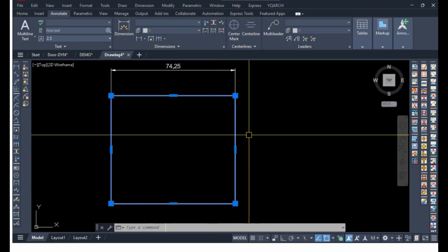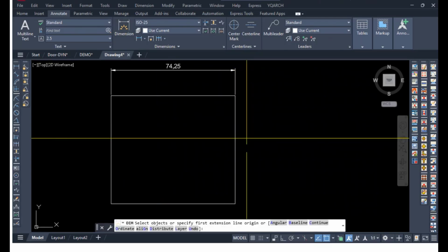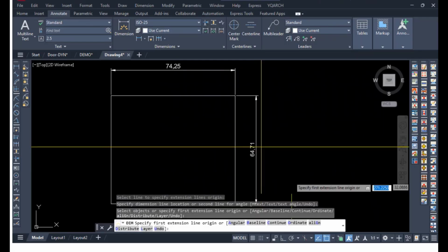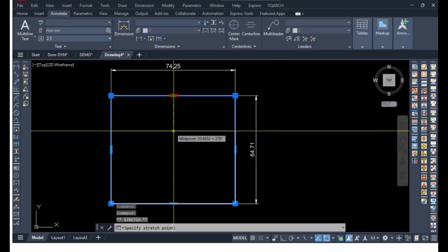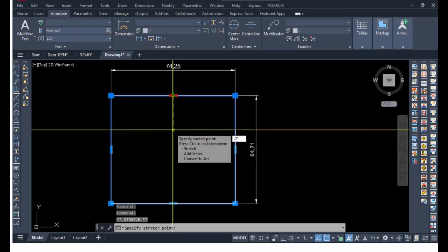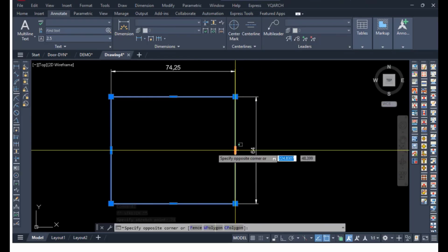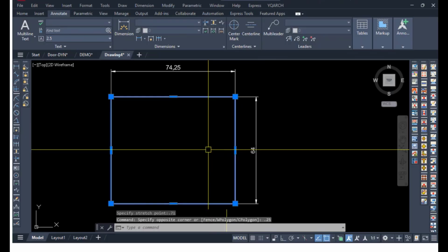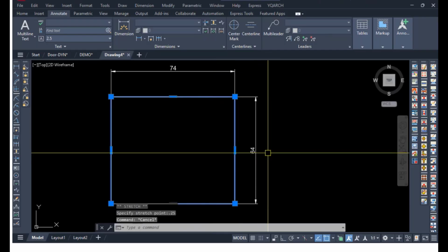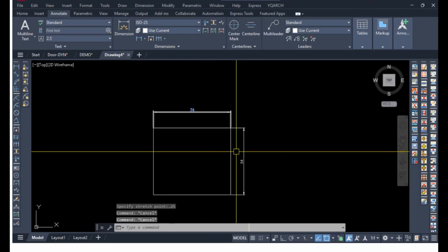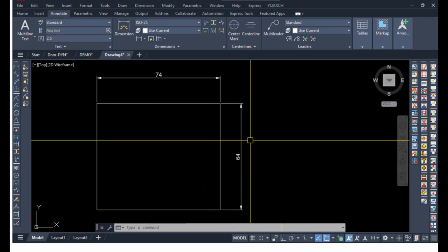Yeah. Then on the other side as well, when we apply the quick dimension here, I need to adjust here to this size 0.71 in order to keep this full number, right? And then this one is going to be 0.25. Okay, we got the full number on both sides. And it's still an associated dimension, you see, very easy, right?